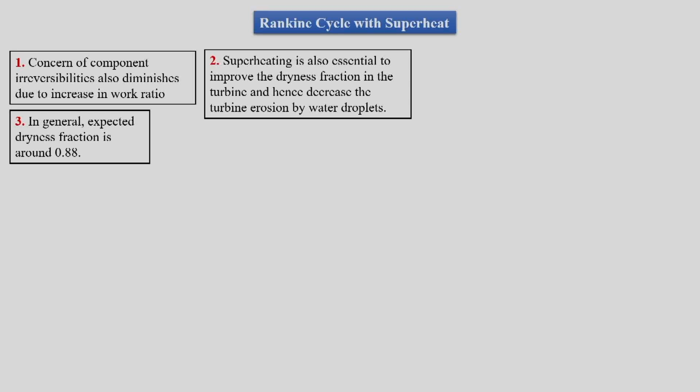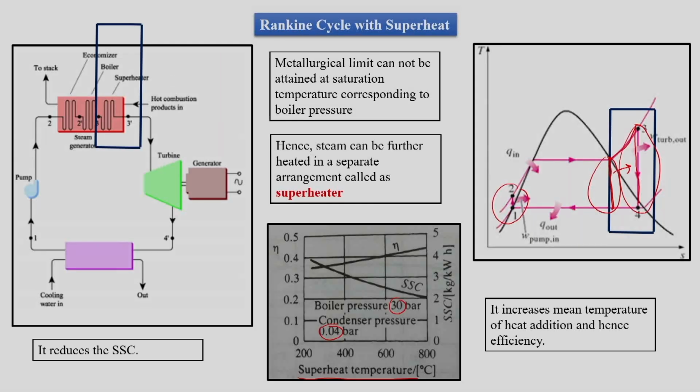Basically, if we have the steam power plant like this, where we have stopped somewhere here. So if we have the entry of the steam into the turbine over here, and if we have expansion like this, then we have only vapor over here and we have liquid plus vapor over here.